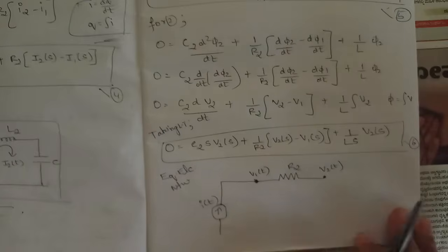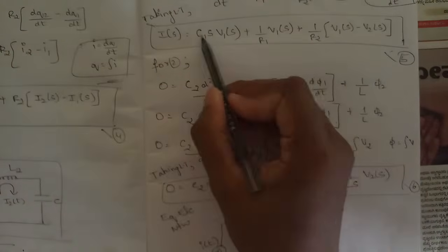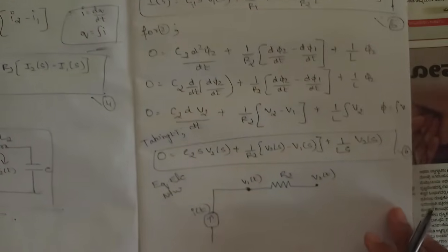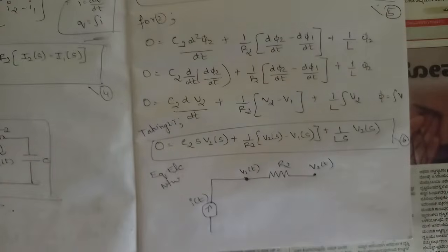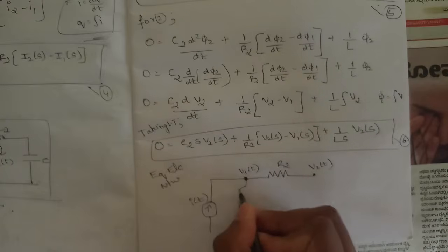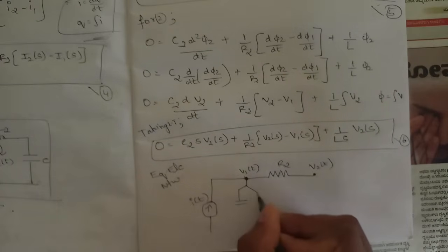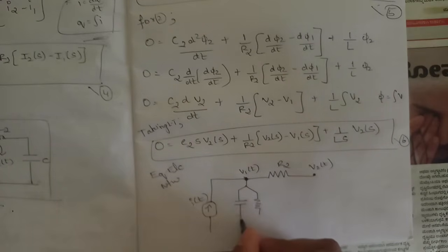So along with V1, what all we have? C1 and R1, but those two should be in parallel. I've told you, right, in the FI analogy the components must be in parallel to each other, and in the FV analogy the components should be in series to each other, irrespective of the node or the loops, okay? So we have C1 as well as R1 in parallel, right?